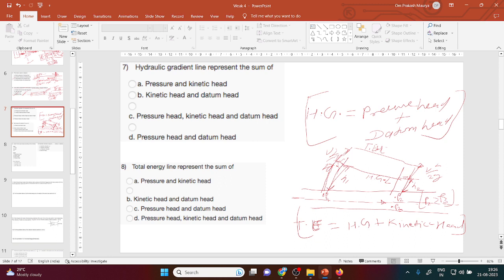So the line will be a bit below as compared to the smooth, frictionless case, right? So if there is friction, then it will be below the hydraulic gradient line, because of the loss of pressure due to the friction. Okay, sir. So the hydraulic gradient line is actually excluding the presence of friction.